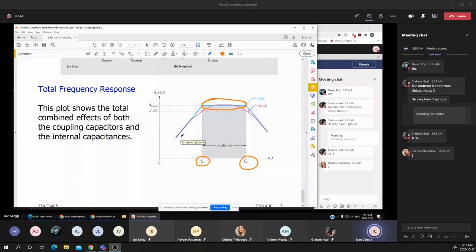An application for that: when you are looking to buy, for example, an audio receiver or an audio amplifier, we are looking at the low-frequency cutoff. This means the vendor will guarantee that any frequencies from, let's say, 20 hertz up to 20 or 30 kilohertz will not be distorted, or the distortion of the waveform on the output has a very small percentage, such as 0.1, 0.01, 0.03, and so on.